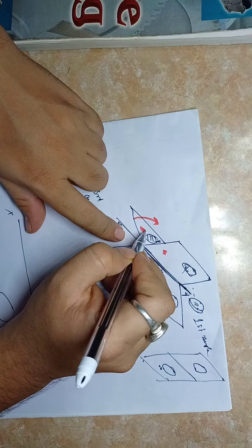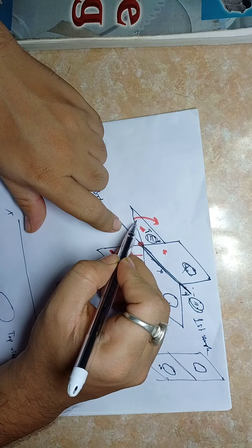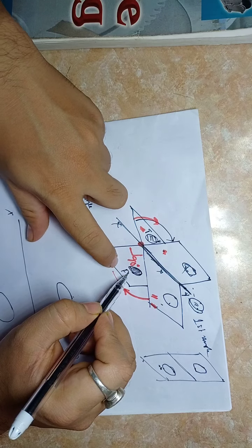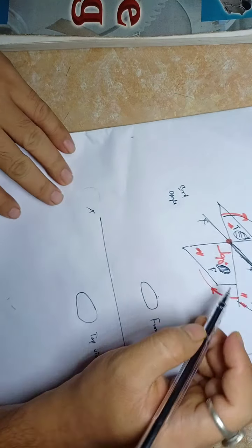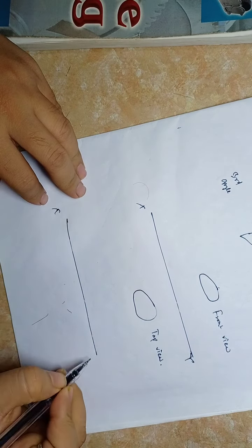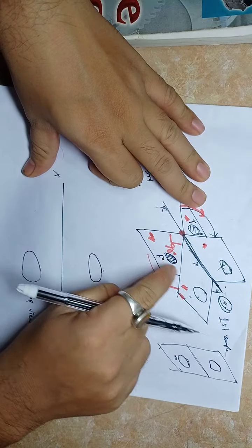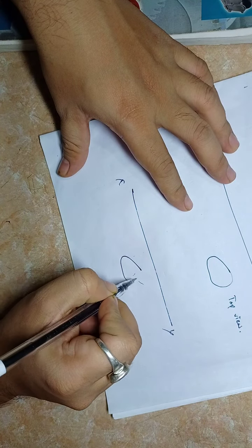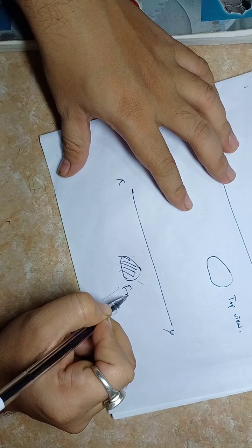Let's write as F here. Top view means T. Now since you have merged this plane here, we have taken this plane above, and this plane is there itself. Okay, we are not changing this plane. So in third angle projection, see, front view is below XY line, isn't it? See, below, it is below XY line, so it will come here, front view.